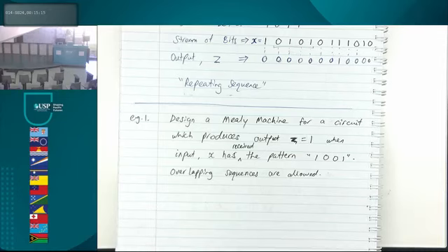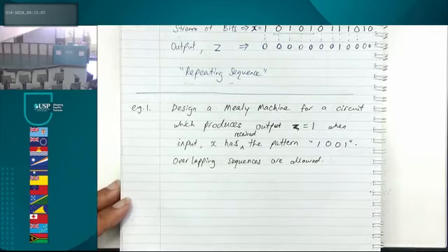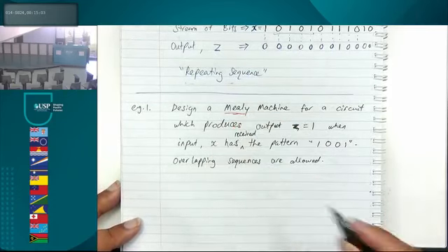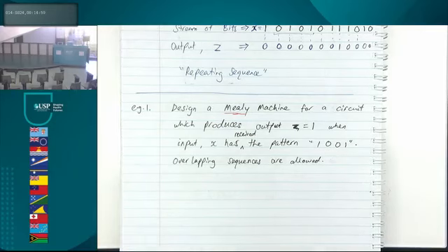All right, now the first thing, we follow step by step. Again, it's a design process, which means we follow step by step. Now, it's a Mealy machine. Mealy machine means, does our state have to accommodate the system output? Does the state bubble, in terms of the state diagram, have to accommodate the output? No. Mealy machine, no. Moore machine, yes.